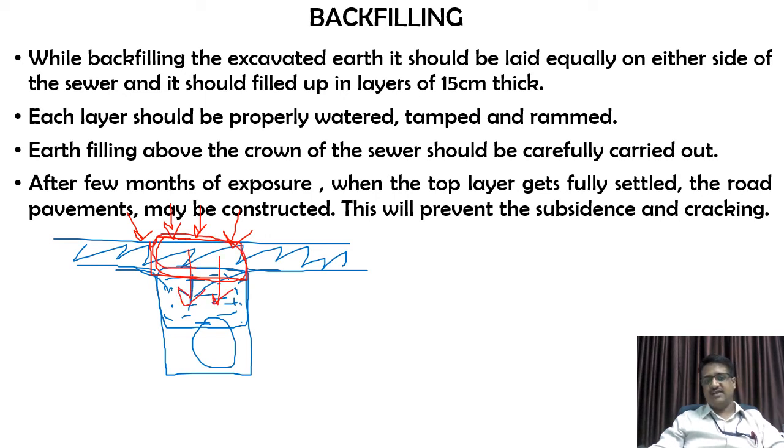So if we don't want such things to happen, we need to make sure we provide proper layer by layer compaction of the soil that will be laid, and provide sufficient time for consolidation or compaction to take place, then the further processing will be done. So that's why even backfilling is an important step. Even putting soil is not enough, you need to have a proper depth, and that's why the watering, tamping and ramming have been mentioned here.